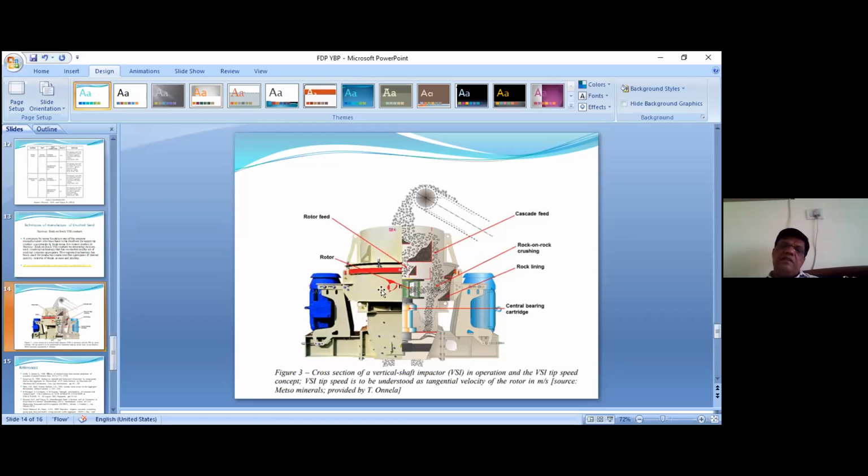There is some waste product also, because our Indian Standard recommends only 15% silt, but here there is 30% silt, so you get only 70% aggregate and 30% silt. Of that 30% silt, 15% we can safely use in the crushed sand, but the rest can be used for land filling. So there is 15% wastage in this plant. In many crushers there is some wastage, because we have a limit in using the silt. So silt can't be avoided.